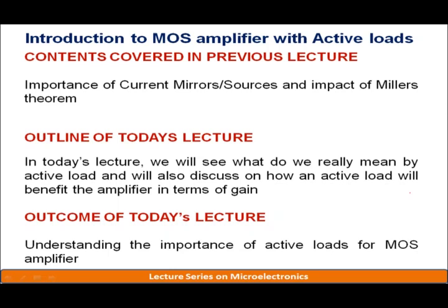because MOSFETs being very tiny elements, I can utilize the MOSFETs in building the so-called current sources, and by using those current sources, I can be using them as a load. So basically, the agenda is the same thing. I'll be using MOSFETs to build the current sources and use that current source as a load. And once students understand all these concepts, they will be in a position to understand the exact difference between the active loads and the passive loads when it comes to the MOS amplifiers.